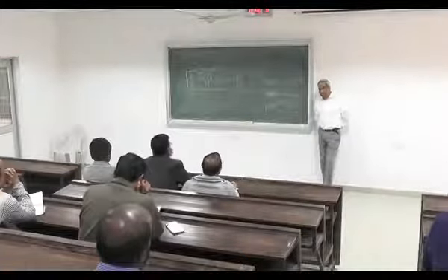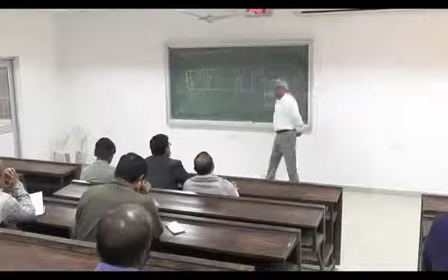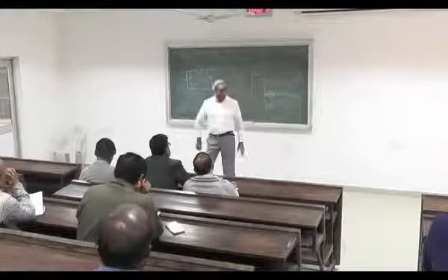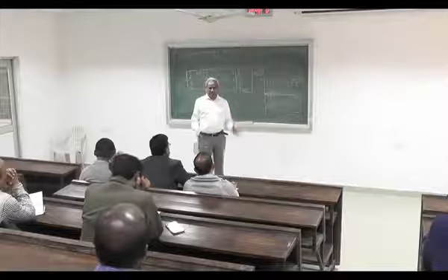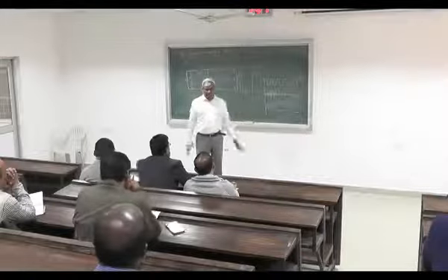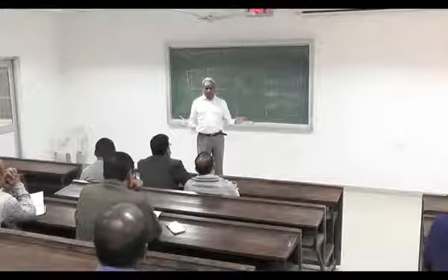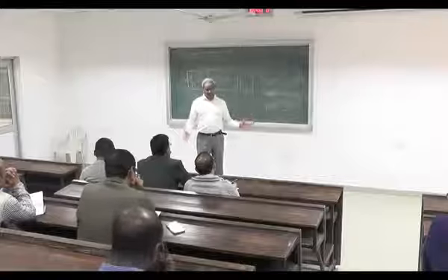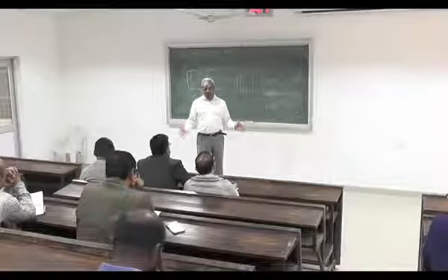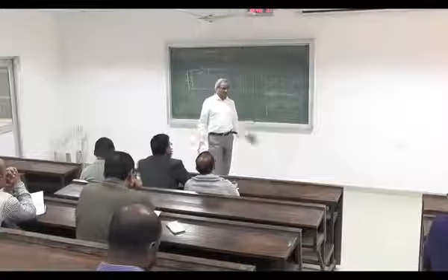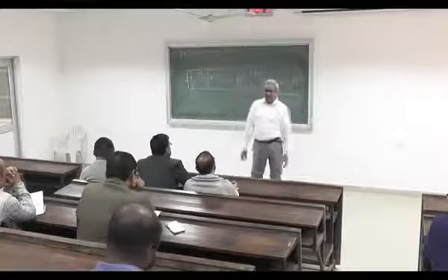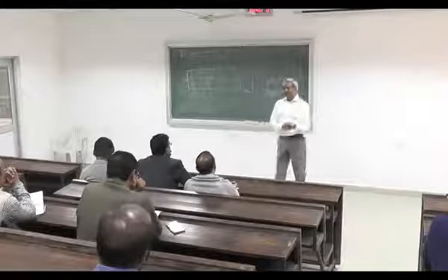When you do digital control, right now we are making the assumption of a 50% duty cycle. Let's say it is 10 megahertz at 50% duty cycle, that's the assumption. But in the first few pulses, the transient, you don't have that 50% duty cycle.